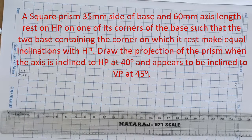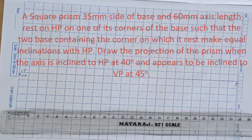A square prism, 35 mm sides of base and 60 mm axis length, rests on HP on one of its corners of the base, such that the two base edges containing the corner on which it rests make equal inclination with HP. Draw the projections of the prism when the axis of the prism is inclined to HP at 40 degrees and appears to be inclined to VP at 45 degrees.